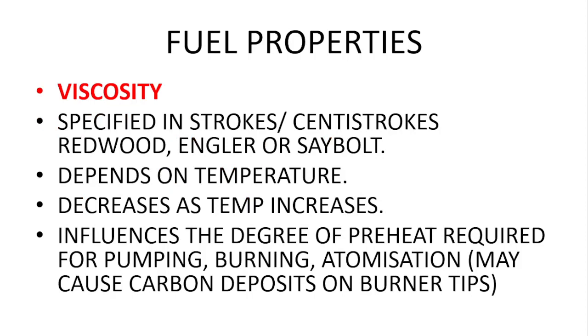The viscosity of liquid fuel is specified in Stokes or centistokes, Redwood, Engler, or Saybolt. It depends on the temperature. Viscosity decreases as temperature increases. Viscosity influences the degree of preheat required for pumping, burning, atomization, and it may cause carbon deposits on burner tips.